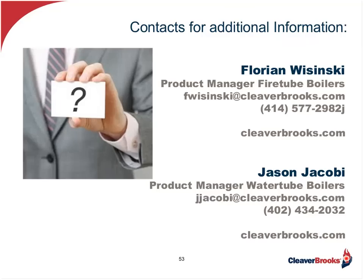Okay. Next question. Does Cleaver-Brooks provide the SCR package typically, or is it a third-party provision? If it's a third party, who guarantees the performance? What Cleaver-Brooks has done on SCR packages, we have pre-designed SCR packages for all our larger fire tubes and our industrial water tubes. So we have worked with the design of the SCR package. We do use a third party for provision of the catalyst and some of the components, but we do have pre-designed systems, and Cleaver-Brooks stands behind the performance guarantees.